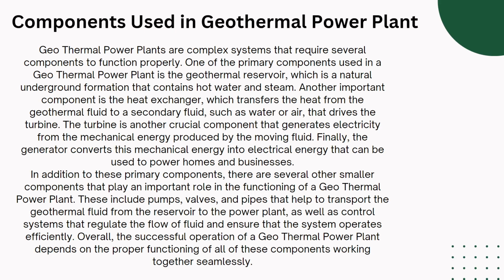Another important component is the heat exchanger, which transfers the heat from the geothermal fluid to the secondary fluid, such as water or air, that drives the turbine. The turbine is another crucial component that generates electricity from the mechanical energy produced by moving or flowing fluid. Finally, the generator converts this mechanical energy into electrical energy that can be used to power homes and businesses.